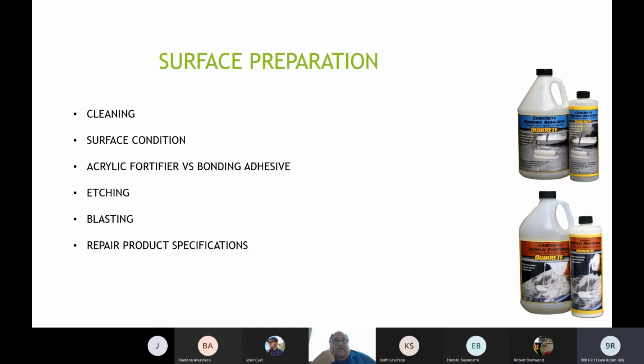Okay, so what you're going to want to do is obviously wait at least 28 days, because concrete's going to cure for 28 at a minimum. So you wait 28 days, and honestly, the only way to get rid of that, you can try using the chemical strippers they have to remove sealants. The best way to test after you've done that, if it works, is to drop water on it and see if the water beads up. If the water beads up, it's still present.